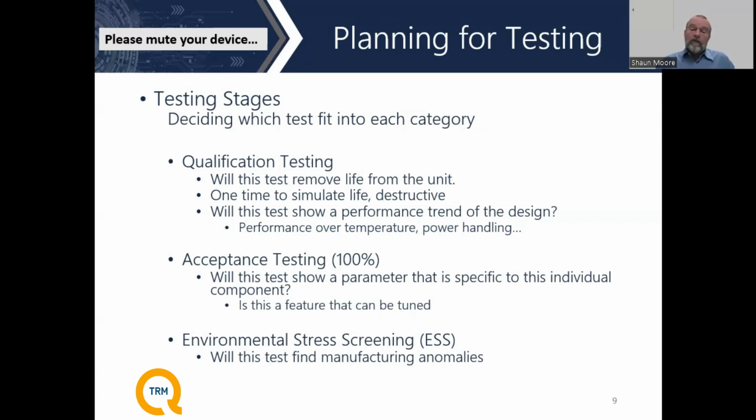The one caveat about these tests is that they're quite extensive, and at the end of the testing, the part will be at the end of its life. We will actually test the part essentially until its useful life is used up. So qualification testing is destructive in the fact that at the end of the testing, even if the unit completely passes, there is no real design life left in the unit, so it really can't be used after that.